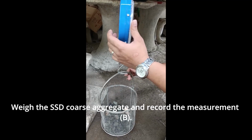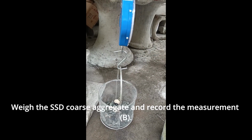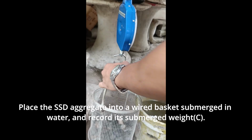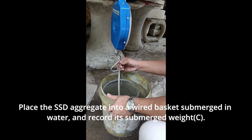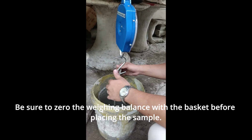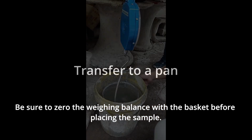Weigh the SSD coarse aggregate and record the measurement as B. Place the SSD aggregates into a wire basket submerged in water and record its submerged weight, C. Be sure to zero the weighing balance with the basket before placing the sample.